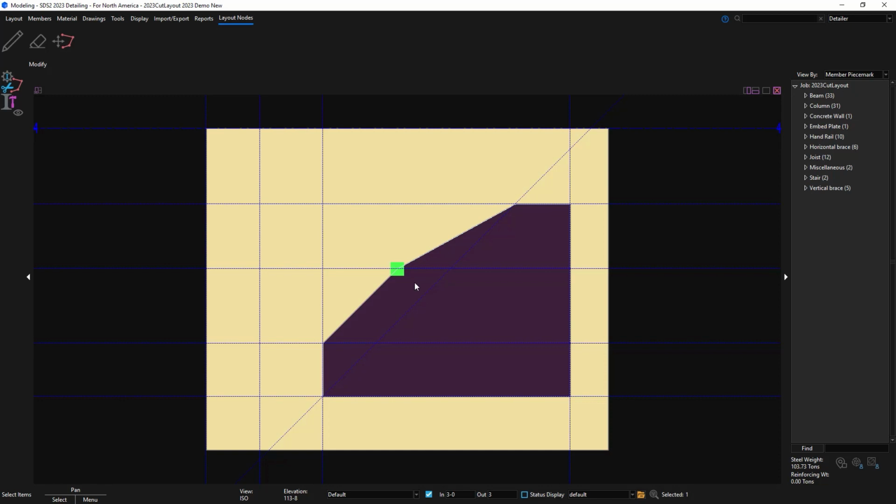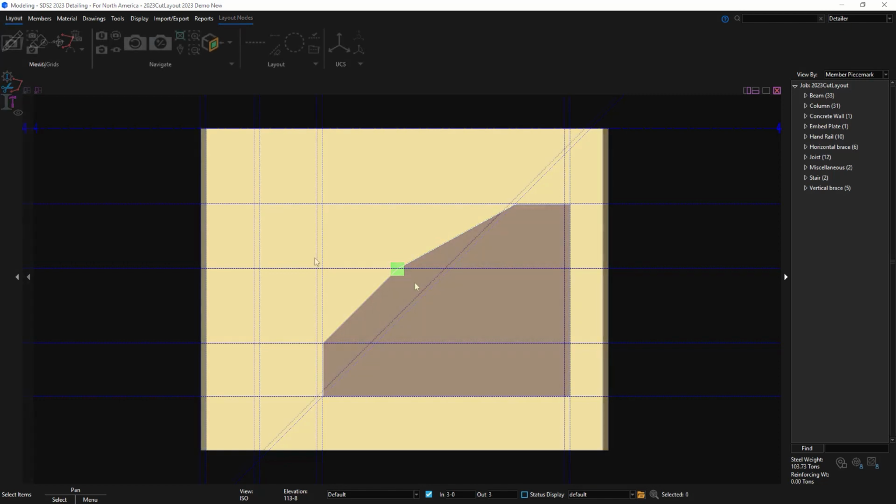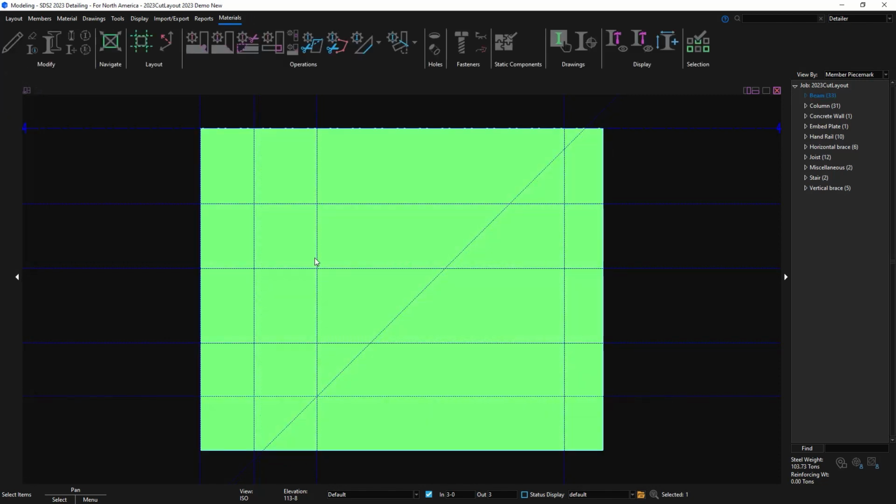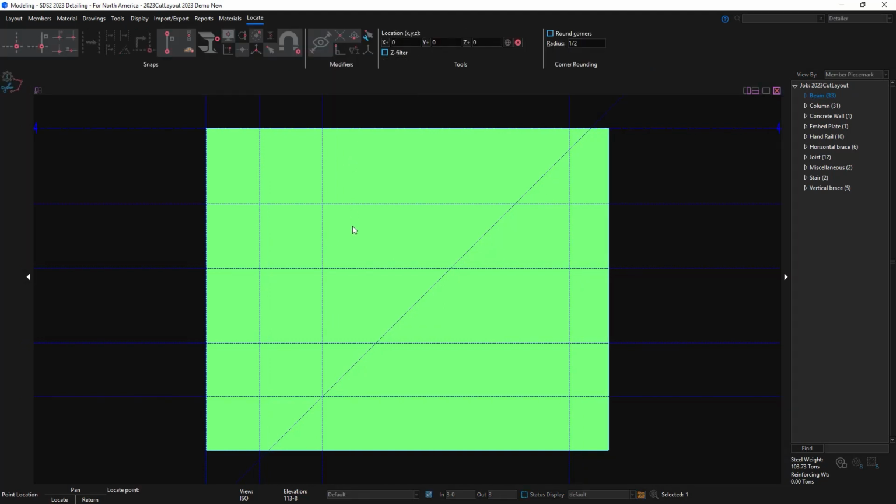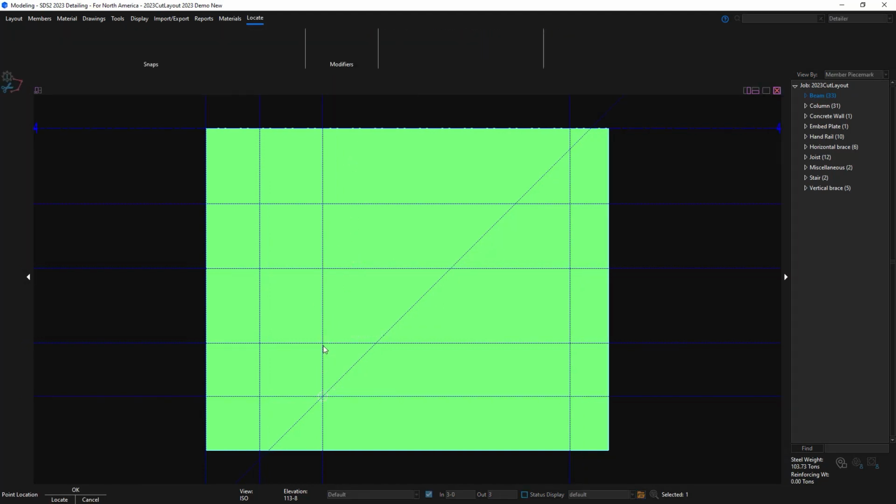Maybe you need to delete a point, add, or move a point because you misclicked. You can now easily modify that cut layout operation instead of deleting and completely re-adding it. To start off, I'm going to select my piece of material and then go to cut layout as we normally would in the past. From here, I'm going to go through and just pick my points.